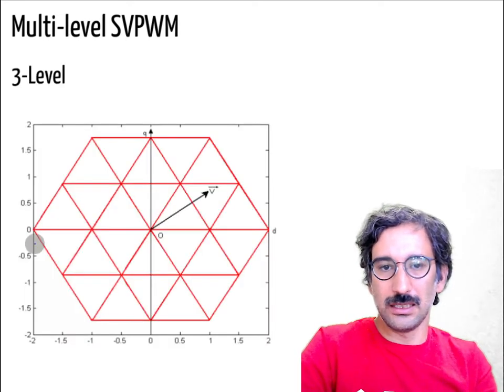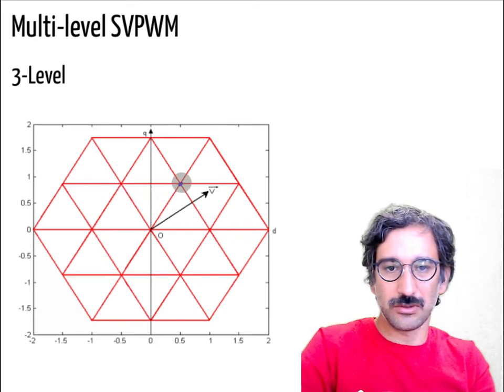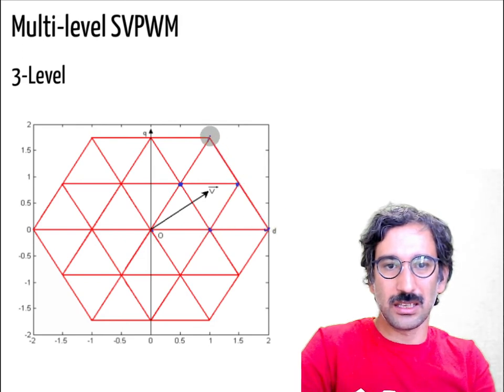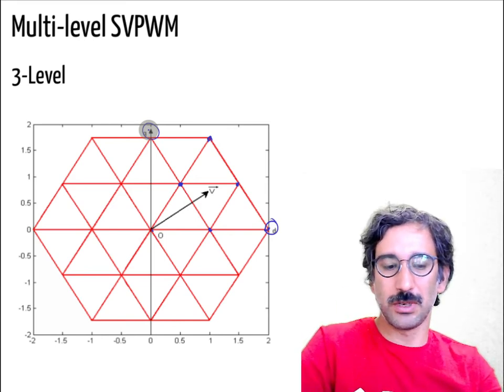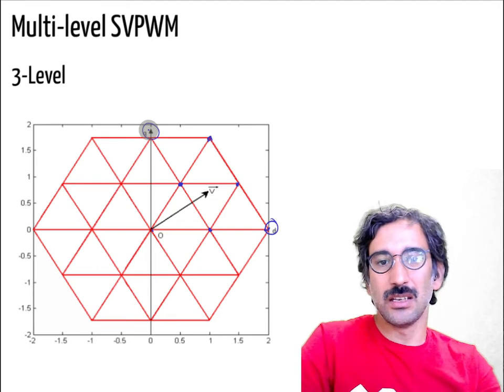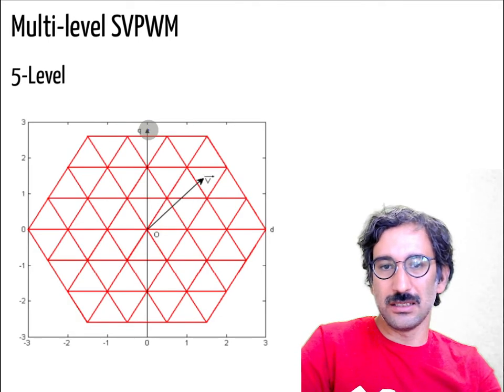So it is like a honeycomb structure with lots of triangles, and each of them can be given a name. Here you see the d-axis and q-axis, the same Park and Clarke transformations, everything is the same. Just how to generate that PWM signal stage is different.